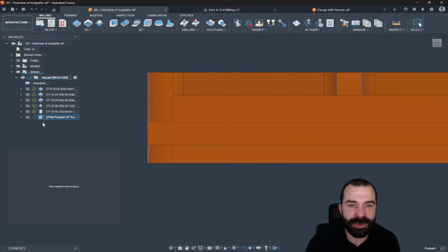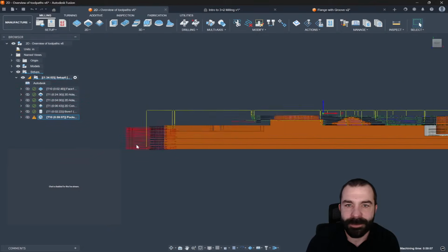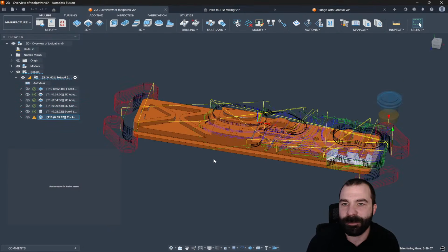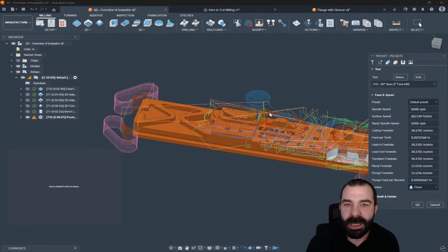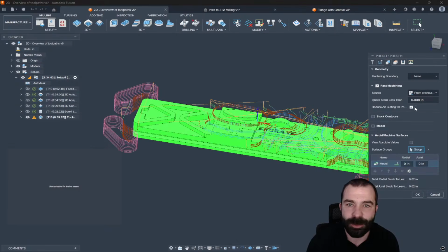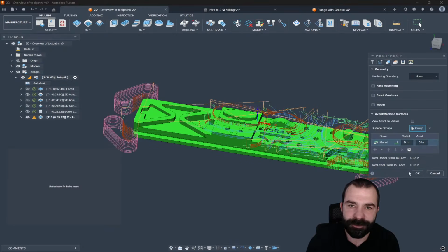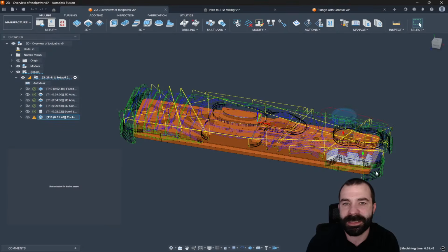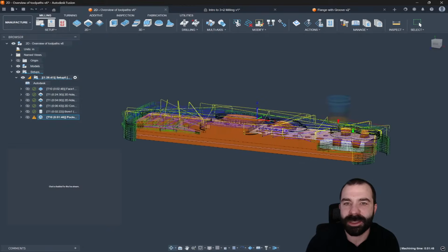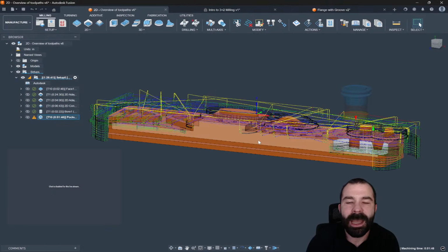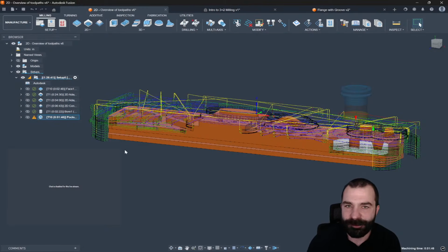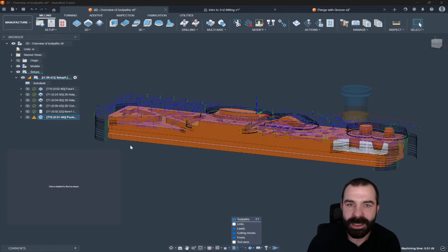Now I will need to drag this toolpath back up to the top because this toolpath does have what's called rest machining. Again, we talked about that on our last week's video. Now I'm going to turn it off for this toolpath because the idea is still the same. As you guys are seeing, I want to start controlling things with the heights tab. I may want to do some different stuff in this toolpath, but from a default, 3D does tend to be extremely valuable to get a very efficient toolpath going in, machining around, and that nature.